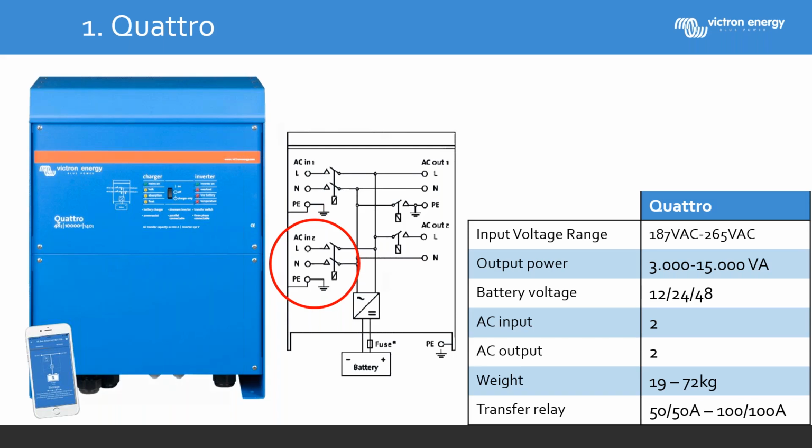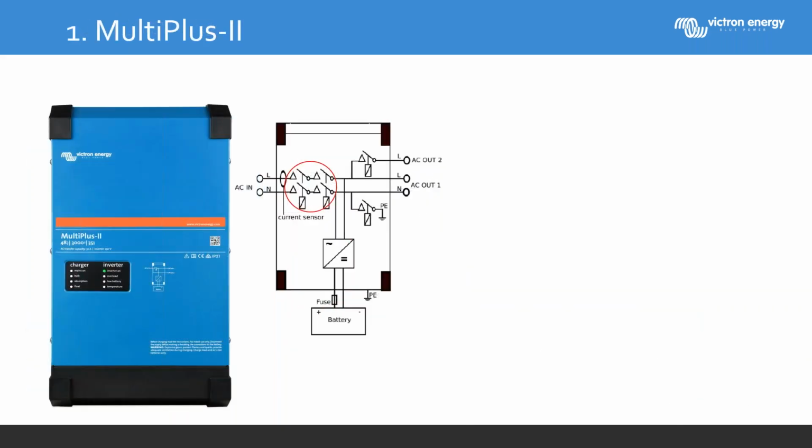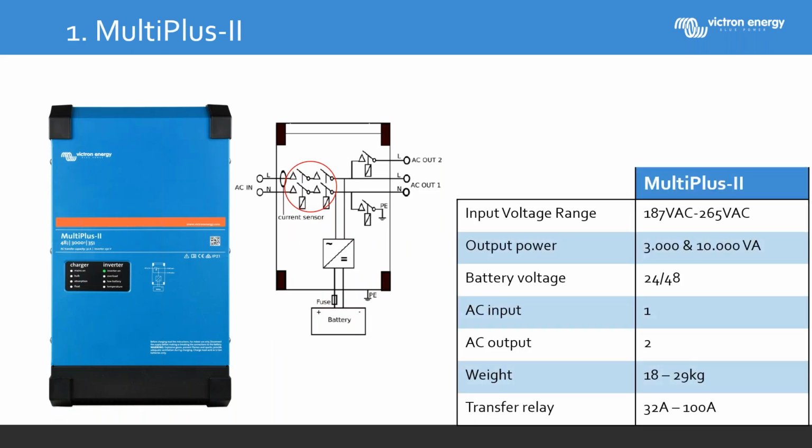And the new range we've been working on for a very long time, it's already been in our product range for 5 years, is the Multiplus II. Internally, if you look at the wiring diagram, you'll see the input contacts or relays. There are now 2 in series for the live and neutral cable. This is what we call the hardwire anti-islanding device that's built into the system. That's mainly for energy storage applications on grid. But this product is proving to be very successful and reliable in off-grid